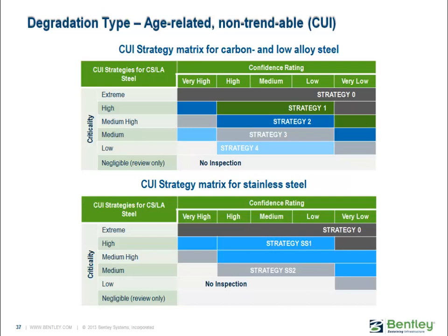The prior condition of the protective coating or insulation and the presence of some chemicals such as chlorides also play an important role in assessing the probability of a failure and make it difficult to assess. Therefore, for corrosion under insulation, a number of inspection or maintenance strategies are developed with a predefined time schedule based on experience. These strategies prescribe the inspection maintenance activities for a long period, and the future action following these activities will depend on the results of the latest inspection and maintenance action.